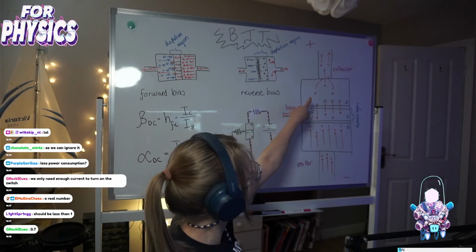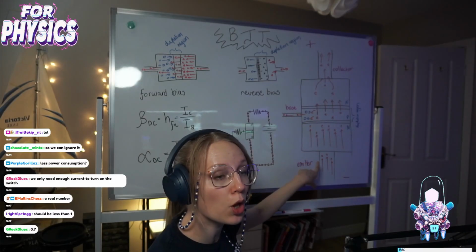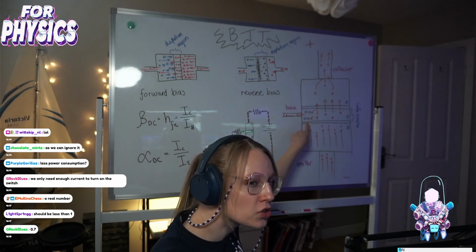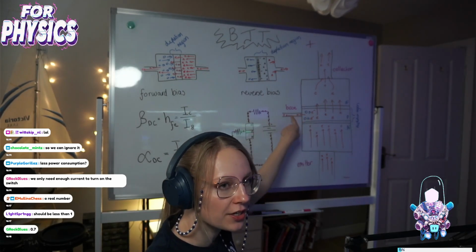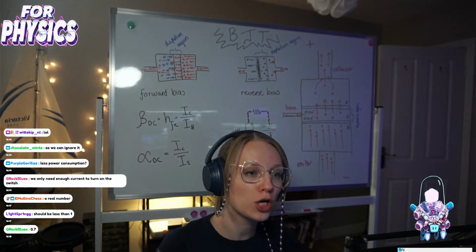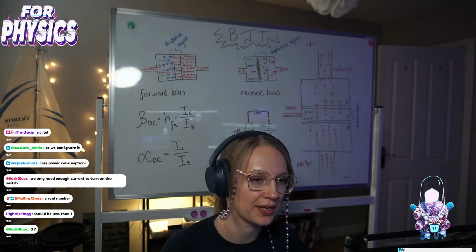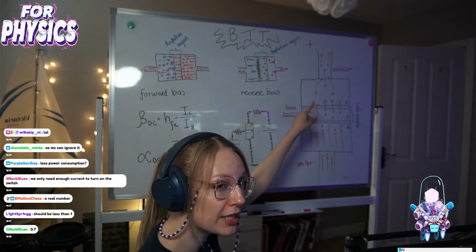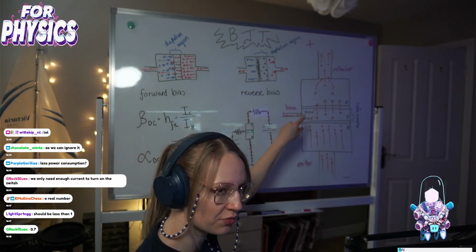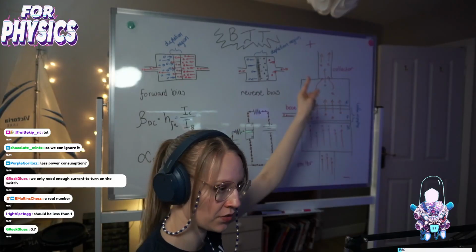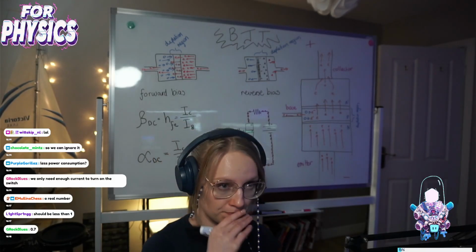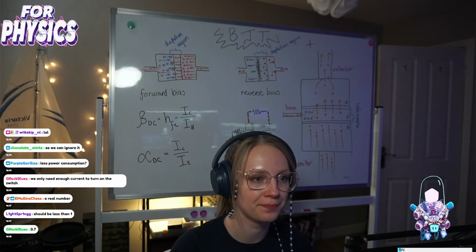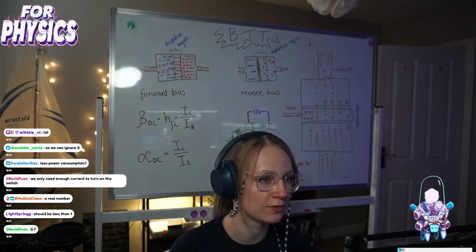So when we put the current from the collector over the emitter, we will always get an answer less than 1, because ever so slightly, some of the current is going to the base. In fact, the closer to 1 it is, the better, generally speaking, because that means very little current is going this way. If it's really close to 1, like 0.99, it means very little current is going here, and most of it is going here, which is very good. But in terms of experience, the alpha number can exist between 0.95 and 0.99. Those are generally good values for alpha.